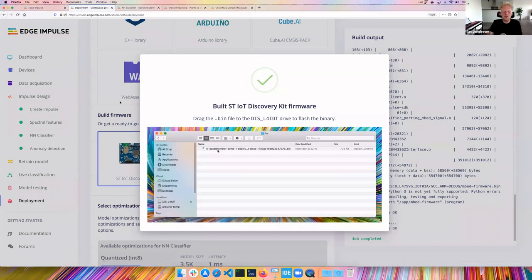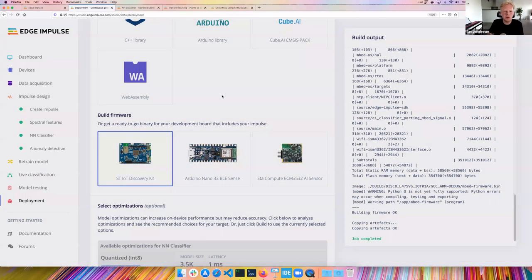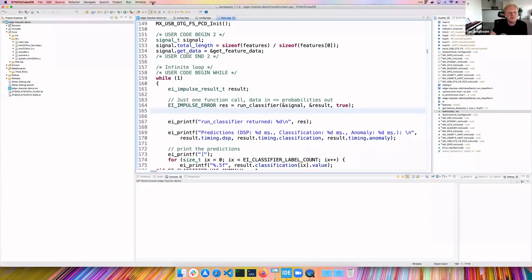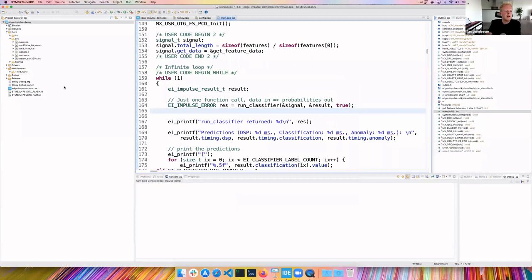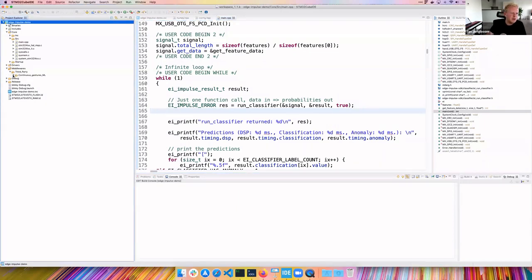So that's the kit. If you include this in STM32Cube AI, what you're going to get is a CMSIS pack. I hope this is visible because my screen is a little bit big. You get a CMSIS pack that you can add like any other pack, like the ARM packs for CMSIS-DSP or anything, included in your project. After you add it, it will show up as a middleware pack here.